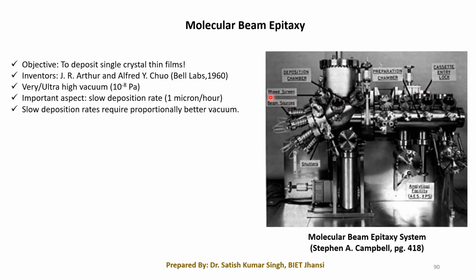RHEED actually stands for reflection high energy electron diffraction patterns. That pattern will tell you the quality of the grown layers, so we have to keep on monitoring it whenever we are growing our monocrystalline layer or epitaxial layer. Fine. Here we are again showing certain analytical facilities. We do have certain other characterization facilities attached over here, and those can give you other features of your grown epitaxial layer.